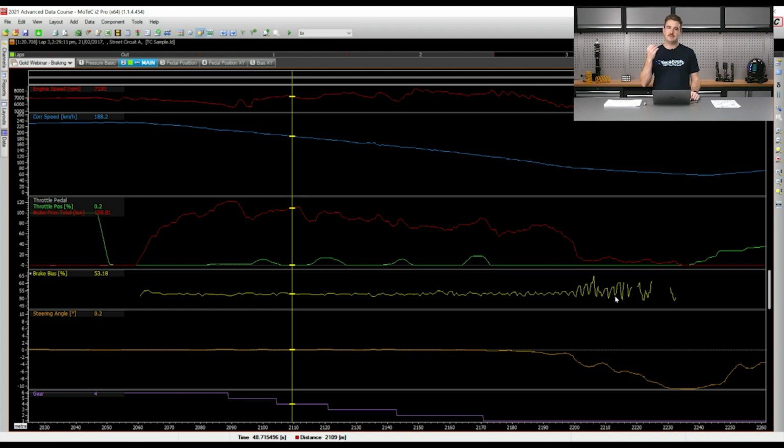So the idea here is that on brake pressure application, the bias is exactly what you set it to with your adjuster, but the whole system is predetermined so that only in the release direction of the pedal, you end up adding a little bit of extra pressure to the rear axle relative to the front that you didn't have before.